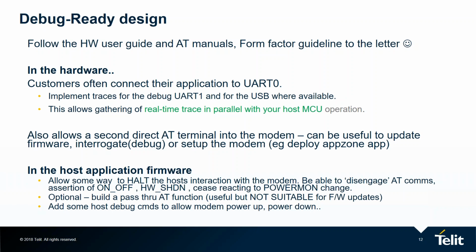In the host application firmware, maybe some software preparation is also useful, again, to have a debug ready design. So allow some way to stop your host doing its normal process of controlling the modem and monitoring the modem and shutting the modem down if it's not behaving. Be able to disengage it. So maybe we have some custom commands, so we can turn on the modem, turn it off, do the hardware shutdown, and stop reacting to the power mon change.